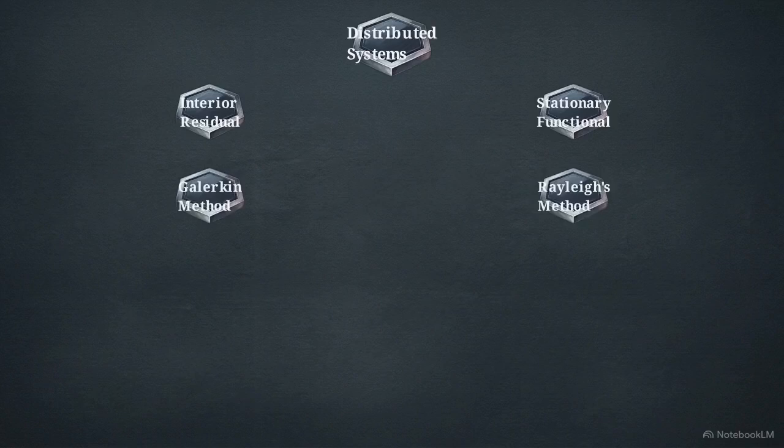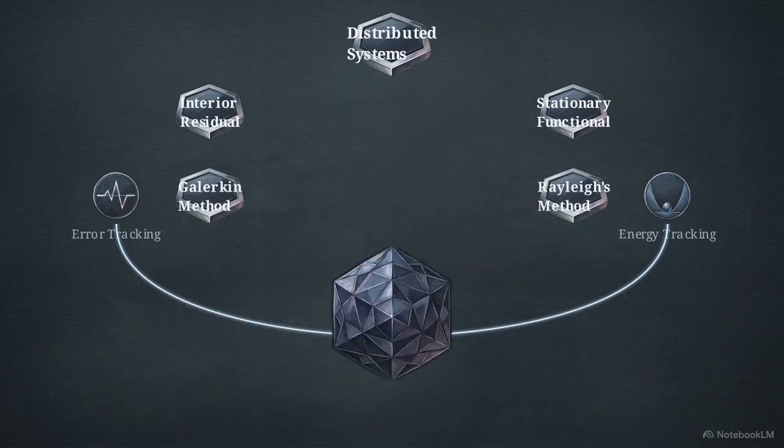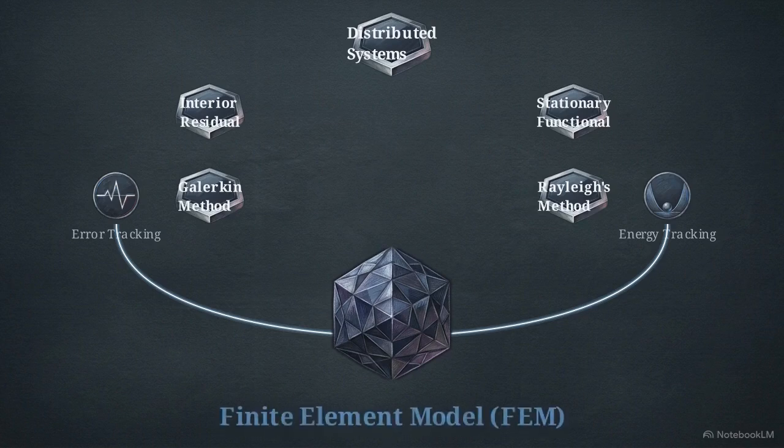Watch the flow of logic downward from the Galerkin method on the residual side and Rayleigh's method on the functional side. Despite utilizing entirely separate sets of mathematical rules, one tracking errors, the other tracking energy, both of these distributed pathways yield the exact same approximate model. Both lineages successfully derive the finite element model. The finite element model stands as the ultimate convergence point of distributed approximation across the discipline.